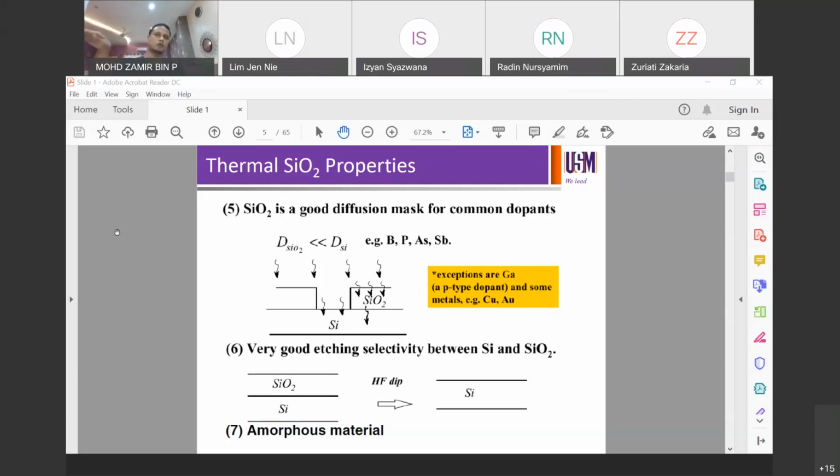So first we will grow oxide blanket, and then you need to do some patterning of the oxide in order to define areas of oxide that you want to keep and other areas of oxide that you want to remove. So for the areas that you remove, the areas without oxide, if you look at the picture on top here, the oxide that is exposed, the oxide that is removed, where you can see the silicon, the dopants will be coming into the silicon from that opening.